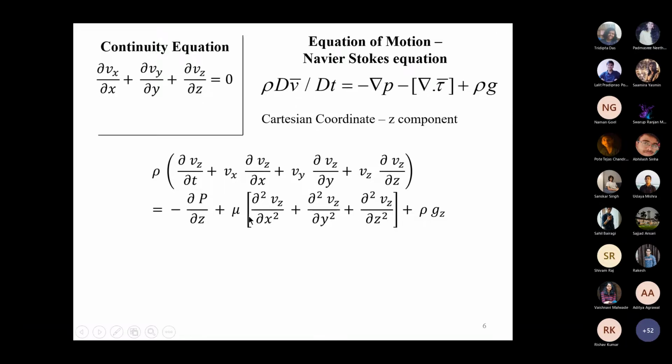These terms, and this is for a Newtonian fluid, so that's why I could write it in this specific form. And for a Newtonian fluid, the appearance of mu explicitly with these terms makes them the viscous or molecular transport of momentum. So this is convective. These are convective transport of momentum. These are diffusive or molecular transport of momentum, where there is no net change in the position of the molecules, but because of their vibration and because of the interaction through viscosity, the momentum gets transported from the faster moving layer to the slower moving layer and vice versa.